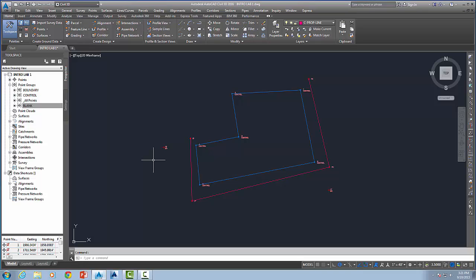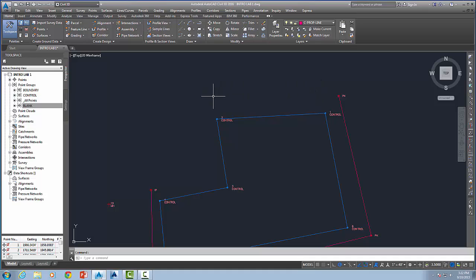Okay. So we're going to establish point 9, and if you look at this and the plat, you have a plat also that is associated with this, and it shows you a final distance of 300 feet and a bearing of north 88°12'56" east. So what we're going to do is establish that point sitting up at point 8, our PK now. And actually I have a railroad spike on my picture I just noticed, but it doesn't really matter for our purposes. So what we're going to do is establish this point from the PK now. We're going to generate a point out along this distance, 300 feet at 88°12'56".